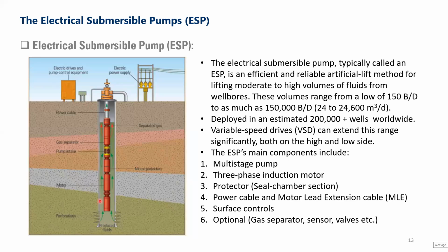And this rotation driven by the motor will give the pump rotation, which gives the pump the capability to produce, because we will start having rotation from the stages, since the pumps consist of stages. So we will have the rotation of the stages, and hence oil going from one stage at the bottom until it reaches the surface, where it will be pumped into the production tubing all the way to the surface. So this is a simple sketch of what an ESP is.